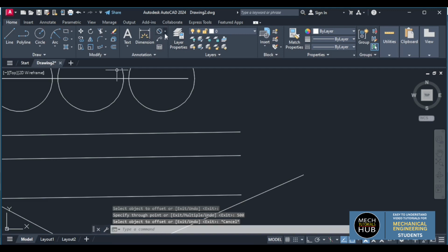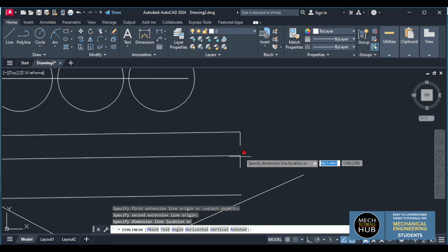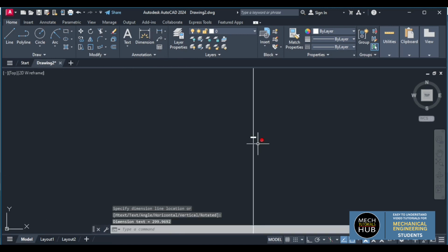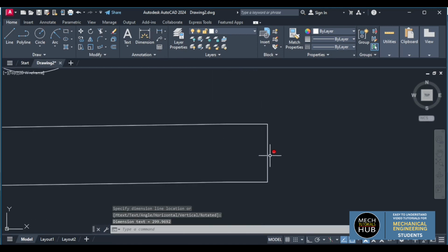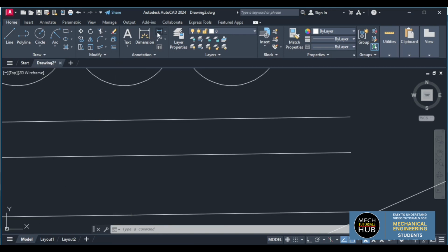That you can check by using linear dimensions. In between these two lines, what is the distance? Check it out. Ortho is off. That is the main reason for the problem between these two lines, and that we can fix. With ortho off, then I can fix it.